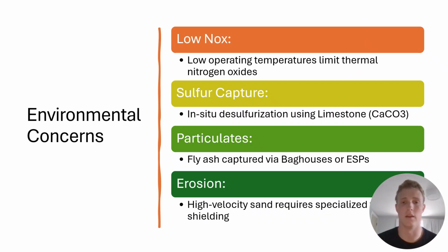All right, now we're going to be taking a look at the environmental concerns. So we're looking at the environmental impact of the bubbling fluidized bed boilers. The fluidized bed is really good because we can operate at much lower temperatures than traditional boilers, which naturally prevents the formation of NOx. We can also solve the sulfur problem inside the furnace by adding limestone, which captures sulfur before it can even become an airborne pollutant.